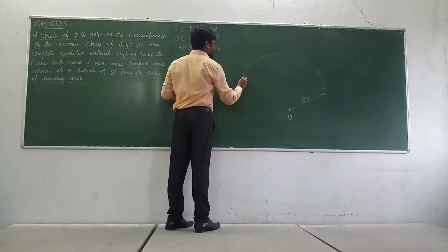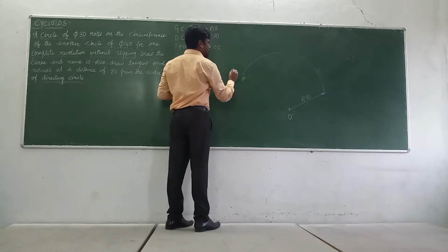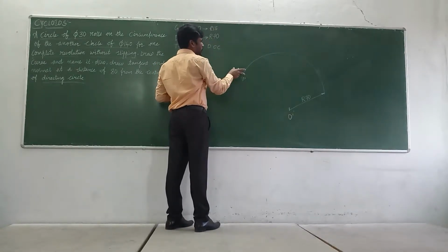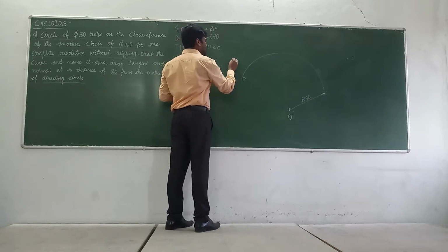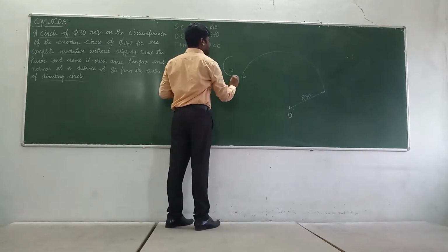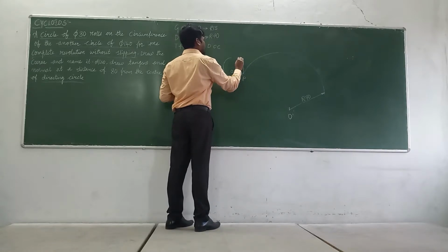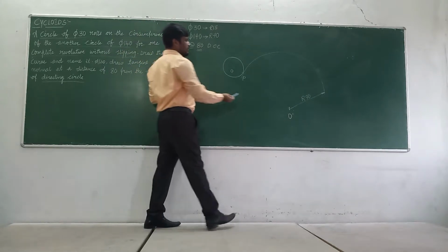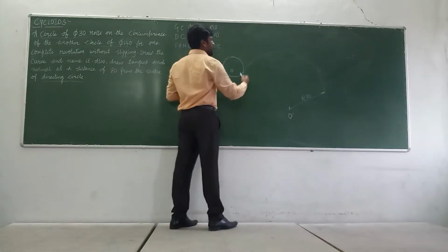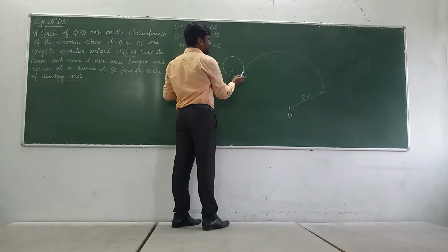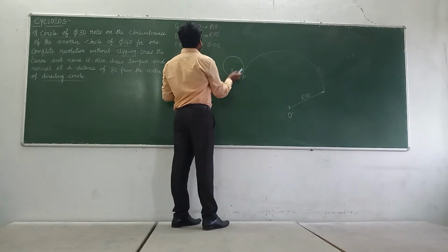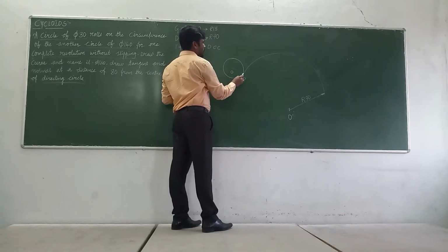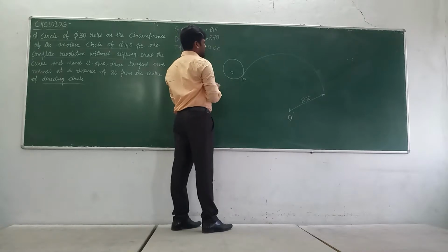That means this is P, my initial point, and this is O. PO is 15, R15. Now with PO as radius and O as center, draw the circle. What I have done? From O dash, draw a line meeting this R, extended from here, R 15. Why? Because my generating circle radius is 15. So P is my initial point and O is the center.